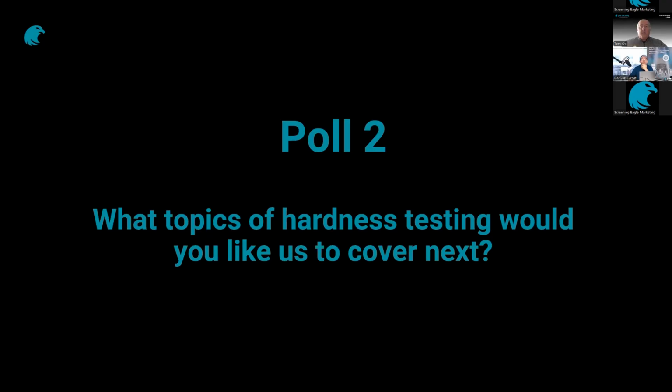We would suggest using a 5 or a 10 kilogram test force to get an adequate depth of penetration on your indentation. Along with that, what I always tell people is the better your surface preparation, the more accurate your test results will be. As a minimum, we would suggest using at least 200 grit sandpaper. In all cases, you should avoid using a grinding stone, because grinding stones tend to build up heat and clog, and building up heat is going to change the hardness and nature of the surface that you're testing.